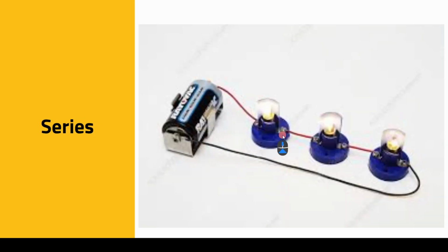Now, what happens in a series circuit if you remove one of these bulbs, or if one of them fuses or turns off or burns away? What's going to happen is that's going to stop the current from flowing through the whole circuit, because that blown or fused or removed lamp acts literally like a switch that has been turned off.